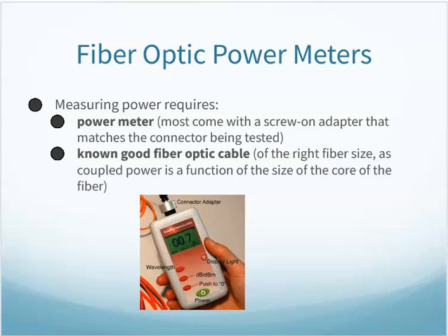All right, CNT140, we're continuing Chapter 8. We just left off on power meters, so I'm picking up right where we left off. To measure power, you'll need a power meter and a reference cable that we use as the 0 point. Here's an example of a power meter.